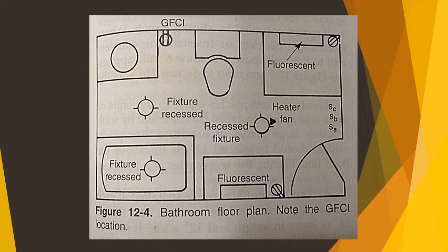Determining the number of branch circuits. Having the proper number of branch circuits on a system will prevent unsafe overloading of the circuits and the nuisance tripping of breakers. Now that you're able to calculate the branch circuit load, it is time to divide the loads into safe and convenient circuits. Article 210 of the NEC outlines the rules regarding the general provisions and specific requirements for branch circuits. These rules, when followed, will certainly provide the safe wiring of the branch circuits.